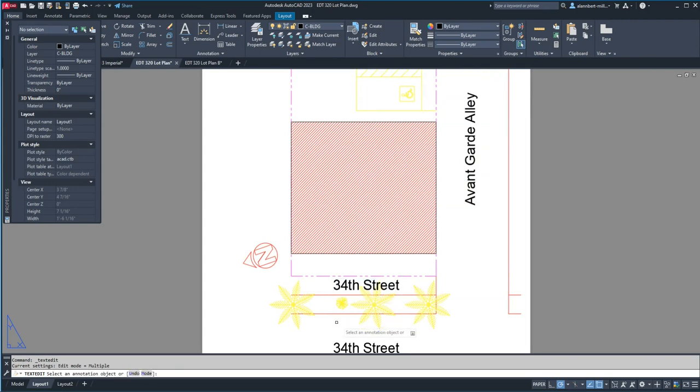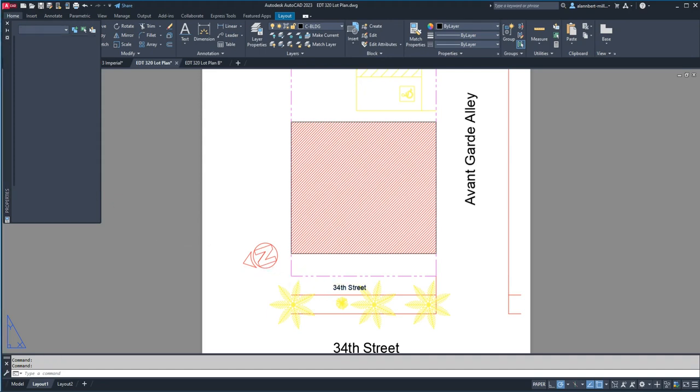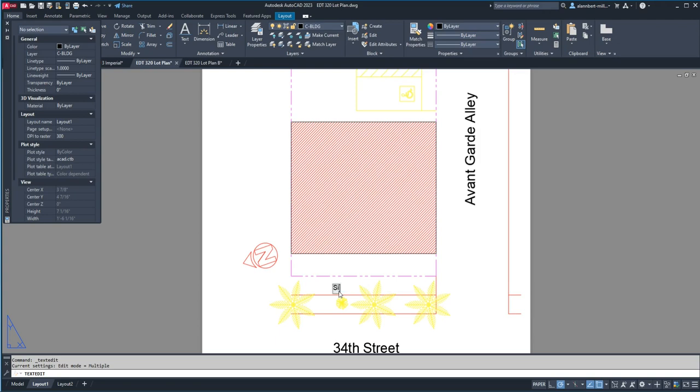To change the height, you simply click and right click properties. But if this box is already here, you can just click on it and change your properties here. So that's too big for me. I'm going to make it half of one fourth, which is 1/8 of an inch. There you go. And then I'm going to double click to edit, and I'm going to put in sidewalk. Okay, and then click outside, and then press escape, and then move where I want it to go.